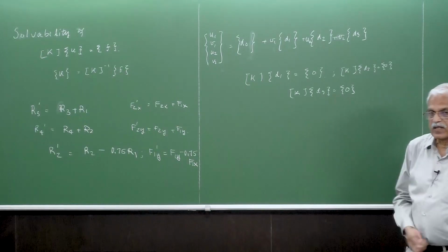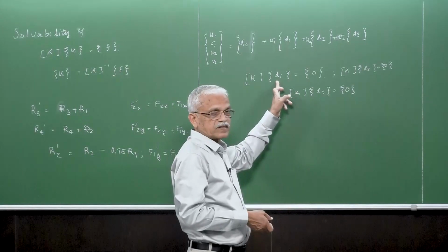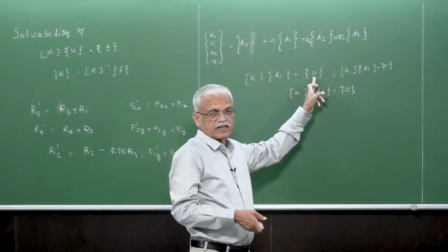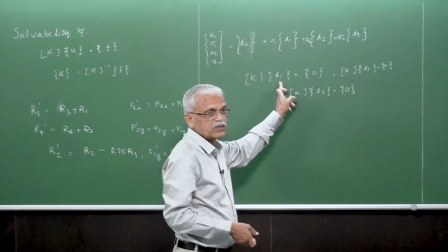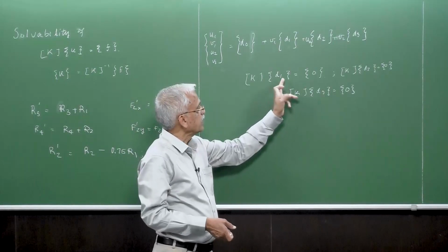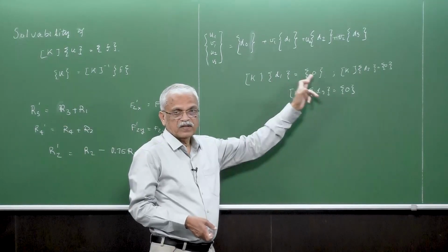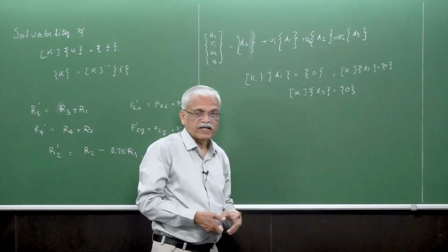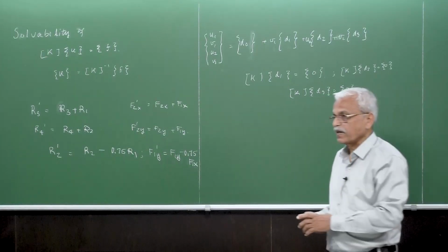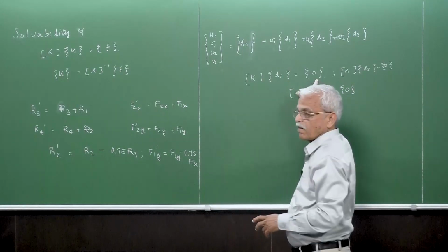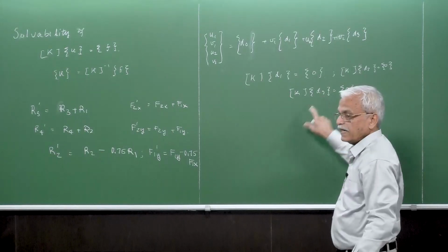This is a displacement configuration for which, if you have configuration D1, the right side represents the force that needs to be applied to get D1. So what does that mean? Without applying any force, you can have a displacement. This doesn't require any force, which means the body is undergoing a certain configuration without the application of any force. Similarly D2, similarly D3.